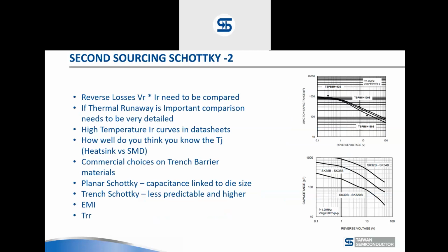The high IR temperature curves in the data sheets, there are thousands and thousands of them. They're difficult to make. You need a guy to sit there, measuring a few samples in an oven in the hall, stabilizing it and that type of stuff. So there are tens of thousands of data sheets out there. Maybe not all of them are accurate in the business. So you also want to measure it in your circuit to make sure that it's done well.